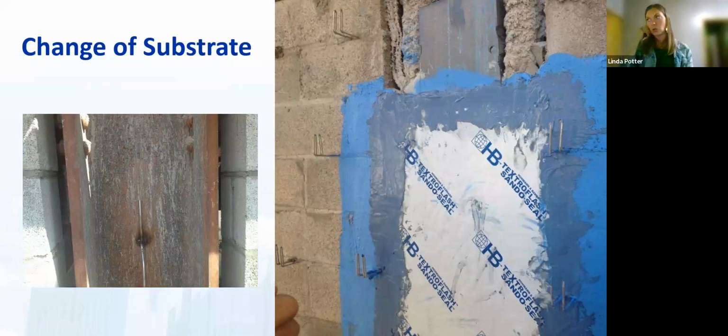This contractor chose to slush it full of grout and wait for that to cure. Then we come back and put transition membrane across that, and then they use some sealant to make sure that the transition material was appropriately fixed to it. But it's multiple steps, and you're the one that's going to decide. Have them tell you what they're going to do, and you decide if that is acceptable or not.